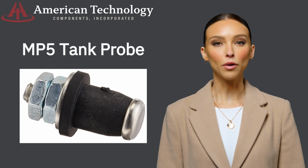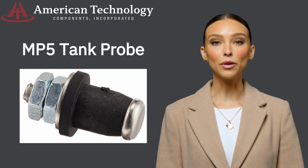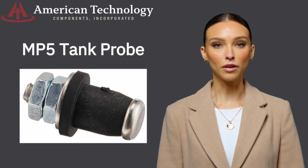The K101 orange, green, and yellow wires are connected to the MP5 tank probe. This is simply an M4 bolt with a rubber grommet, washer, and 2 M4 nuts. The only warrantable failure of the MP5 tank probe is a failure of the rubber grommet. Other possible issues with the MP5 tank probe would include excessive corrosion on the head of the probe, resulting in